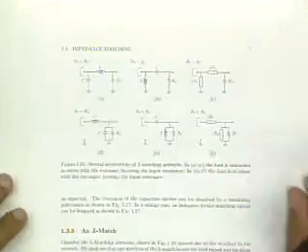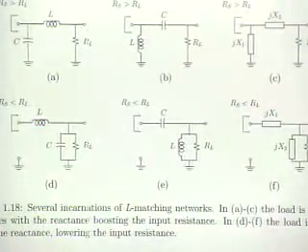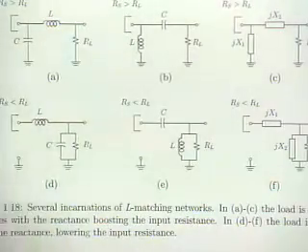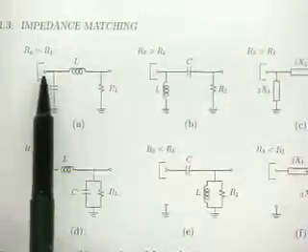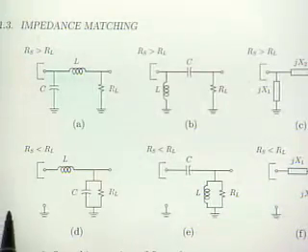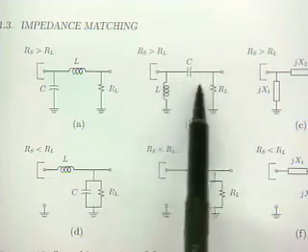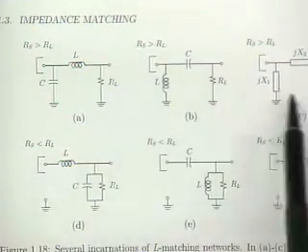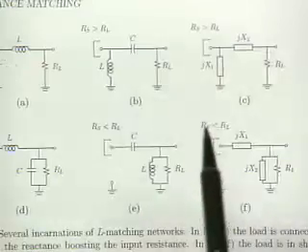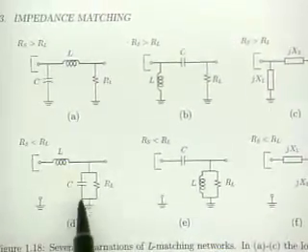Okay? I think I have a little table in here that we could look at. This is from the chapter that you guys have online. So here, starting out here, we see RS is bigger than RL. That's why we connect the inductor in series with RL. We could also do a capacitor, right? This same thing. Or in general, we use complex reactances. This is the opposite case. We hook it up the other way around. We put it in parallel.